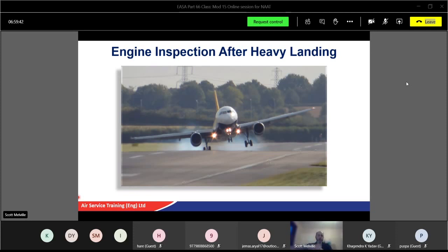You know, the shafts are going to bounce on the bearings. So potentially you could damage the bearings. You might have to do checks on the chips, oil systems, lots of different things. Check fuel range control, the movements, the throttle movements, and all, especially if it's an older style where it's all connection rods and cables. Fly-by-wire, well, it's very hard to check that. But certainly for the older style, you have to check free movement of the controls.